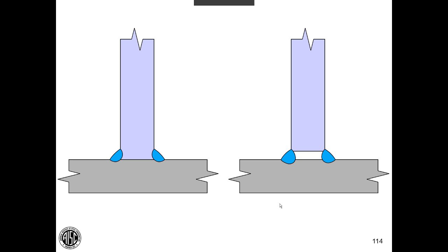Okay, great. Thank you. The next question. AISC Section J5 allows for a 50% increase in fillet weld strength when load is transverse to weld orientation. This seems to contradict the watch your roots statement. Why is this configuration stronger?